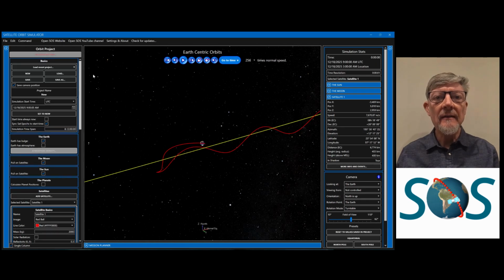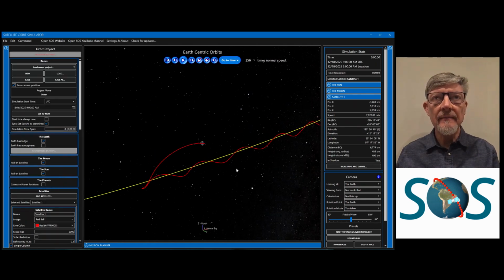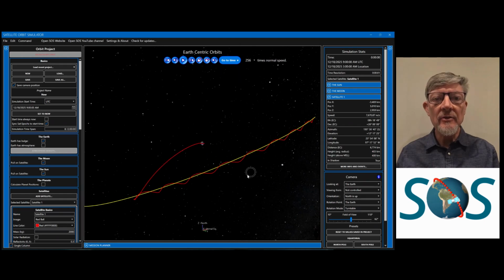As you can see, there is much trial and error associated with designing this mission. Just remember that there are few windows in time where you can reach the moon from this parking orbit. Theoretically, there should be 2 for each lunar orbit around Earth, or 1 about every 14 days. And each of these windows will have its own width in minutes or hours. The width of this window will be a function of how close the inclination of the initial parking orbit is to the inclination of the moon's orbit.